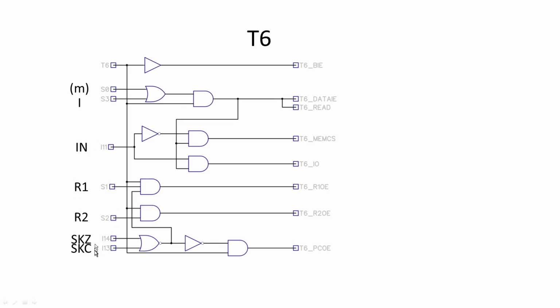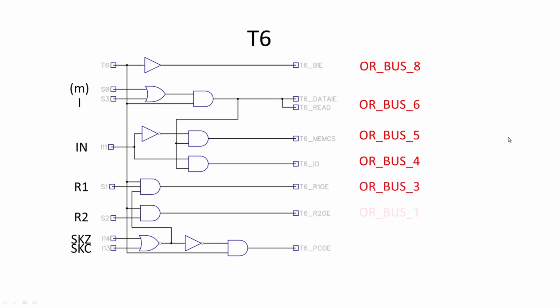You think, well, why don't I just leave them as zeros on the addressing mode? Because you could put this signal here up into this AND gate, so the memory direct addressing mode wouldn't come on. Yeah, but unfortunately, when you use a memory addressing mode, that also increments the program counter, which we don't want to do. So we use the R1 instead. It was just a sort of a cheeky bodge. Again, these signals, that one just goes straight out to there. These two are combined for there, and we use a few more there. So these are all the actual lines it goes out to.